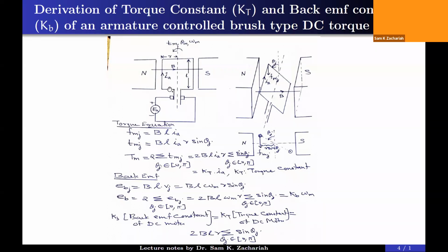Depending on the polarity, north pole or south pole, changing, we switch the direction of current through the coil through a switching circuit. That is called brushless technology. But anyway, the final equation for the brushless motor and the brush type motor will both be the same. But this is easier to understand.